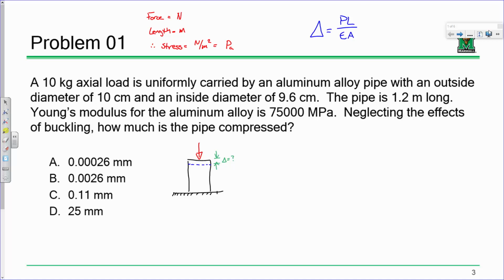And so if you recall, at least when I taught the course, for axial load, the amount of stretch is PL over EA. And then for torsion, if you take TL over GJ, that'll give you the total angle of twist, right? So you take a member, you yank on it, it gets longer. You take a member and twist it, it rotates, okay?